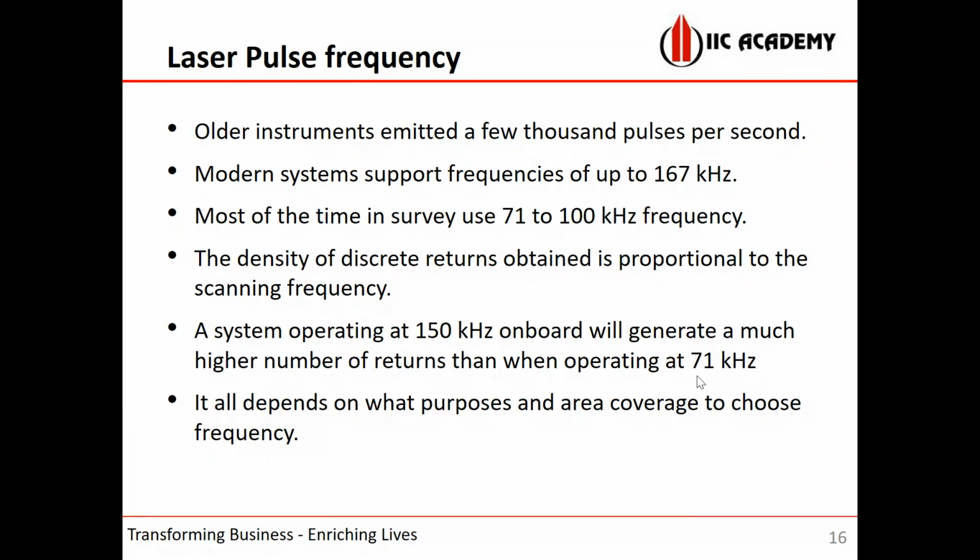We use the same data for bathymetry, and we also use it for extracting topographic information for the coastal region, around 50 kilometers inland. So choosing the frequency all depends on the purpose and area coverage. That's a very important thing actually.